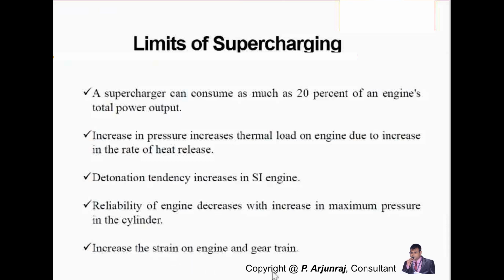Again, this is driven with the help of a belt, a gear system or a chain system to the crankshaft. So the increase of the load will also increase the load onto the crankshaft, and again the design of the crankshaft. That's why you need to do some modification with respect to the crankshaft, not the modification with respect to the powertrain point of view. Powertrain in the sense I'm talking about transmission.